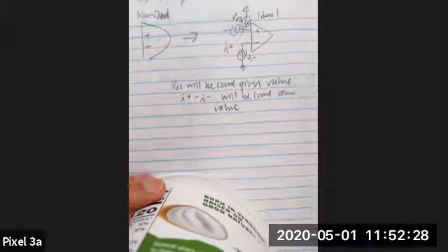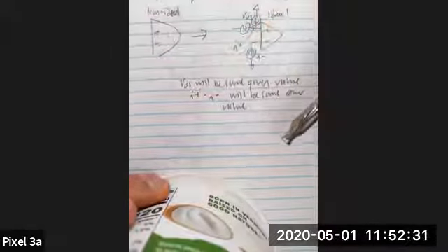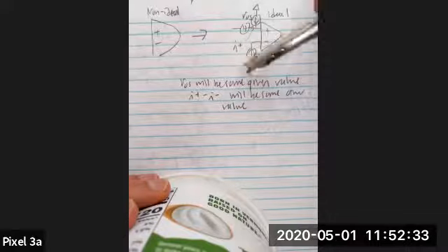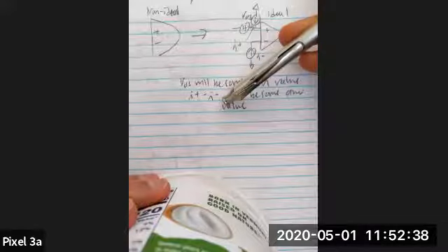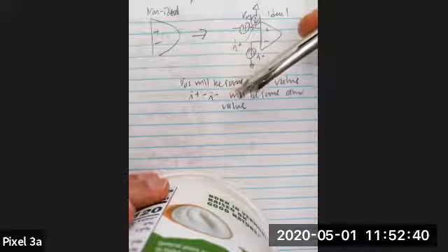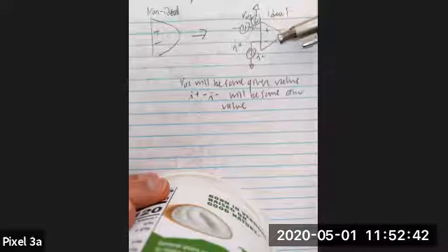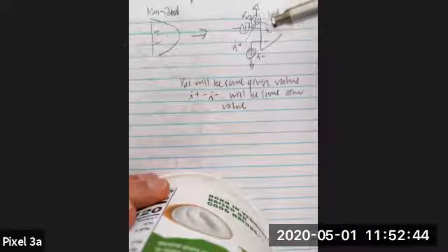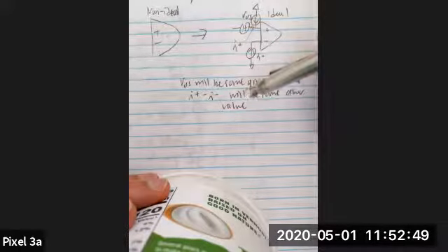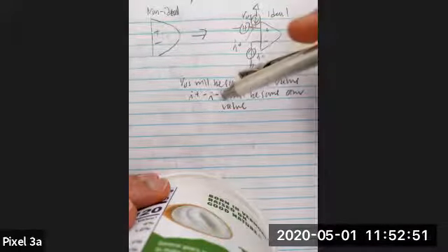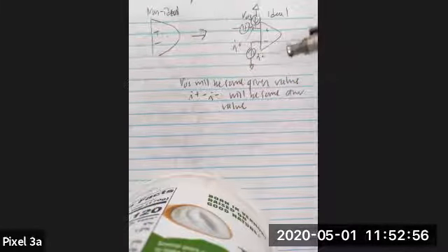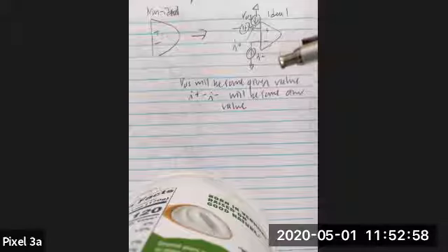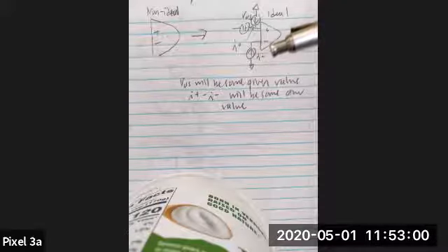The reason we give it like this is that these input currents come about frequently, simply because it kind of depends on the circuit technology. They're given as a difference because which terminal takes in more current depends on which configuration the amplifier is put into.